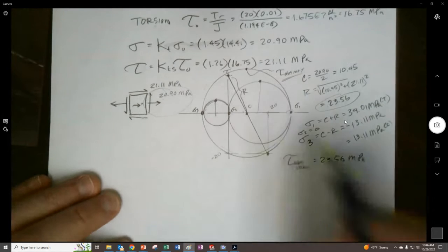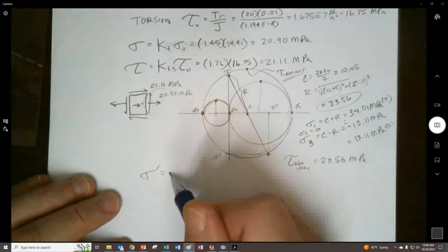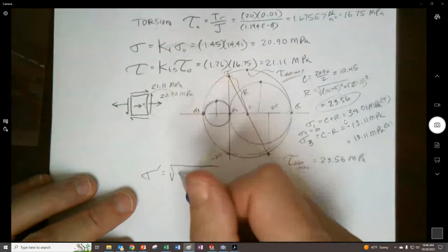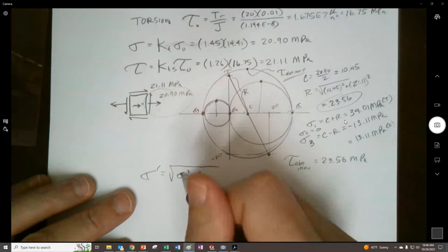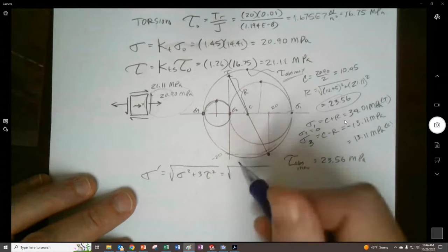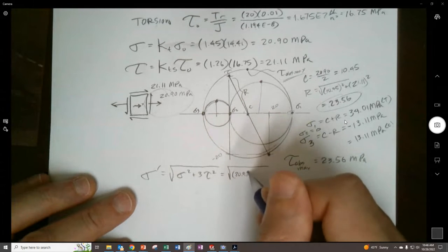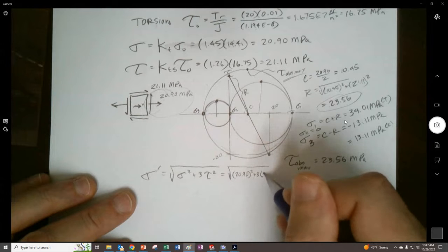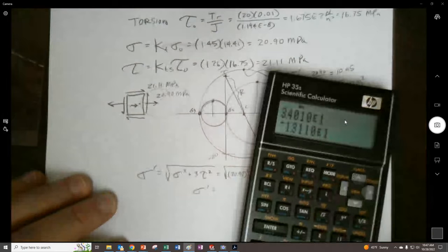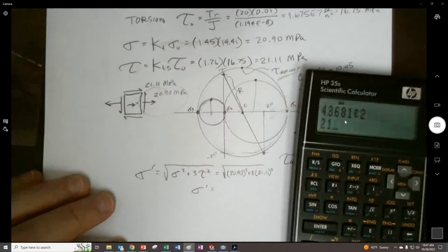Abs max is equal to 23.56 megapascals. And for the von Mises now, because we have a very common condition of uniaxial stress, we can just say that it's going to be sigma squared plus 3 times tau squared, or 20.9 squared plus 3 times 21.11 squared. So our von Mises stress...